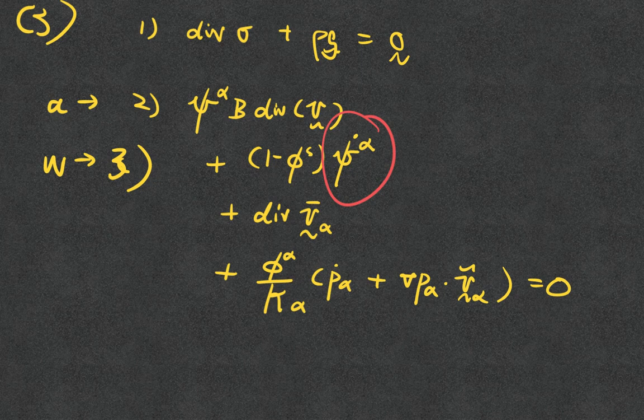So in principle, the elements you can use are still very rich, but one thing that would work is a Taylor-Hood element that has 9 nodes. If you use a quad element for displacement, that gives you quadratic polynomials, and you can use the 4 corner points to form a linear basis for P, and also linear for PA.